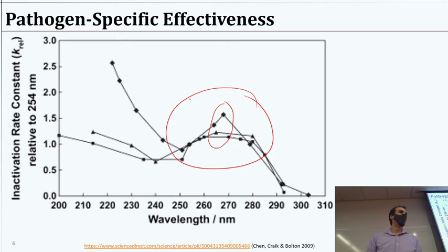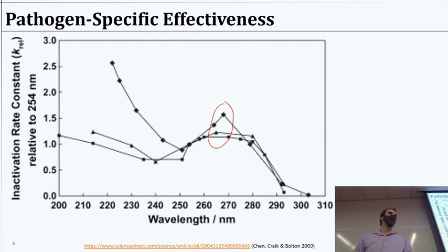It works pretty well. And so as we're designing UV processes, it is important to consider how susceptible a given organism is. Some may be easier than others. And then you want to design for your most difficult organism to kill. This applies to chlorine or other disinfection techniques as well, right? We want to be able to remove enough of the most difficult ones to achieve the disinfection. That builds in a safety factor, and then probably we go a little further and make sure that we've done that much and maybe then some, right? So that's our typical design goals there.